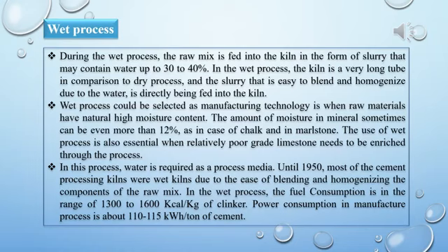He said that in the wet process, you can use the raw material which may contain water or moisture, even more than 12%. It is in the case of chalk and marl stone. He also explained that this is also an advantage of wet process, as you can use poor grade limestone in this process.